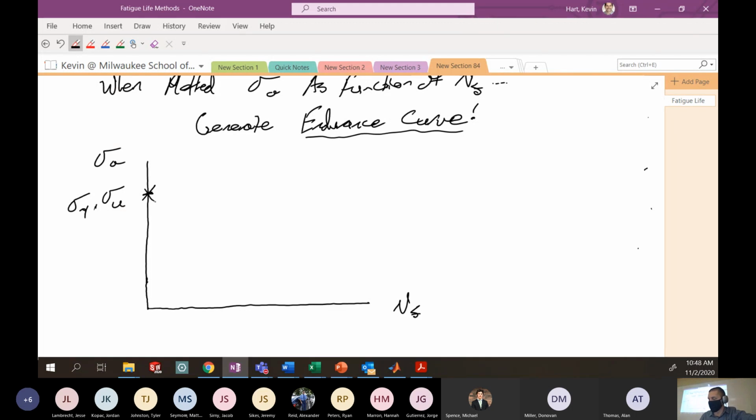How this data typically looks then is as you decrease the stress amplitude away from what would be static ultimate failure, you allow yourself more cycles to failure. So, in the pencil example, my stress amplitude when I was very aggressive was very high. So I only had a few cycles to failure. That would look something like this. Okay. So here I'm decreasing the stress amplitude. So how large is my sinusoid? And because of that, I'm getting more cycles to failure. Right?